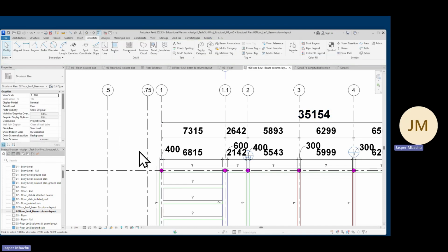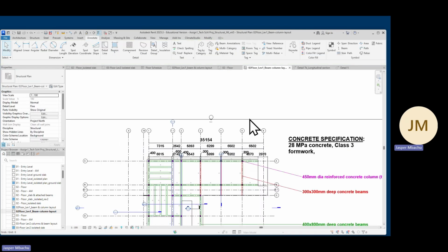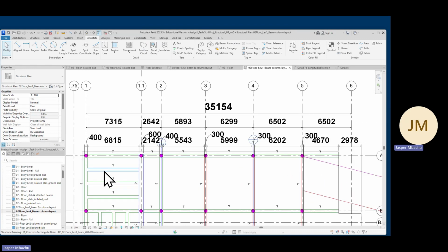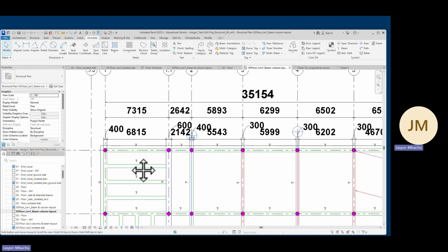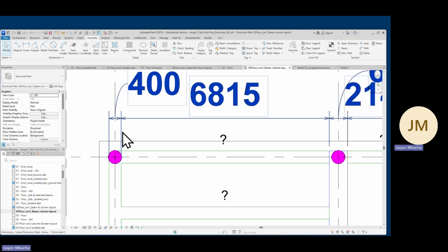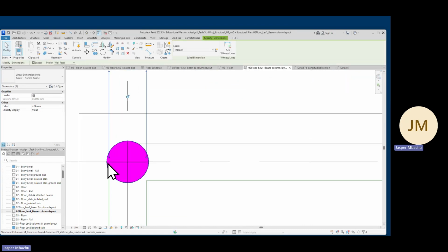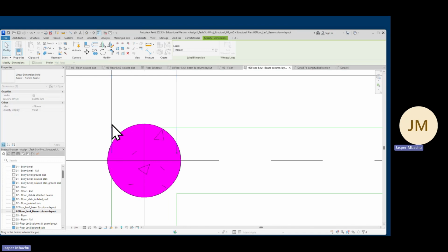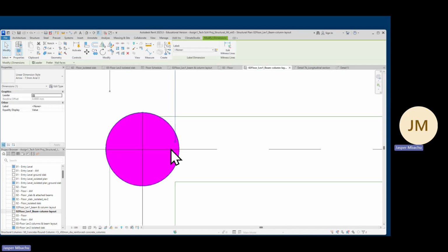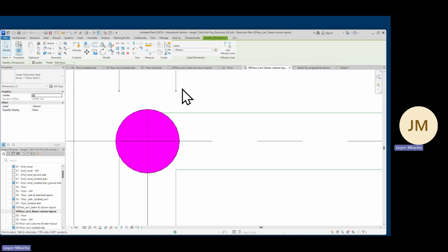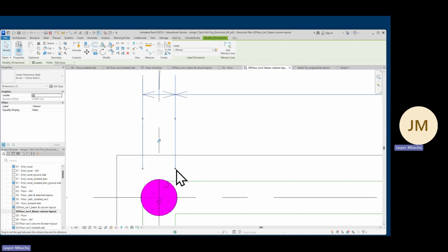Okay. Now, this is how you annotate your beams. And one other thing you might do to help clean things up is when you click on this grid line, make sure that the grid lines are not within your drawings. So just go up and take them away from your drawings.